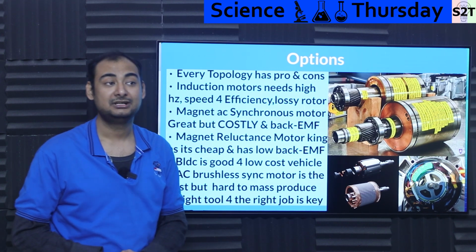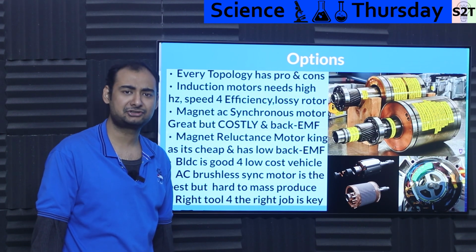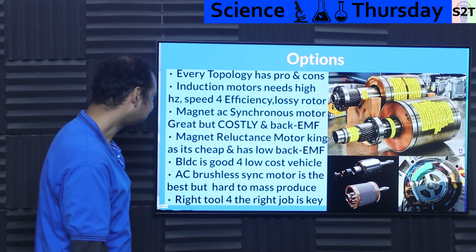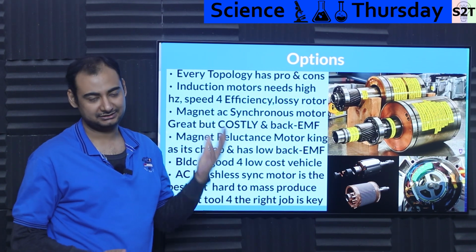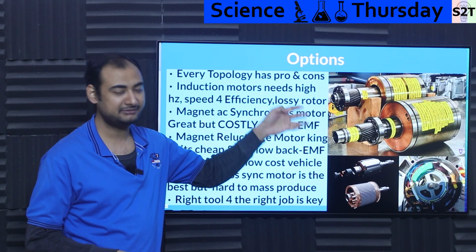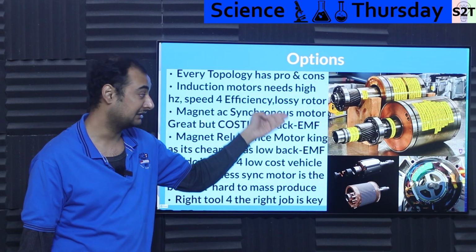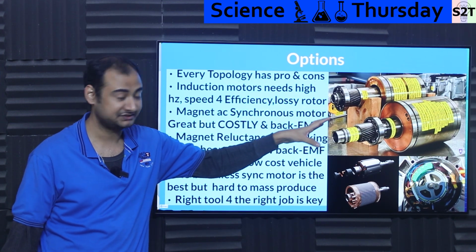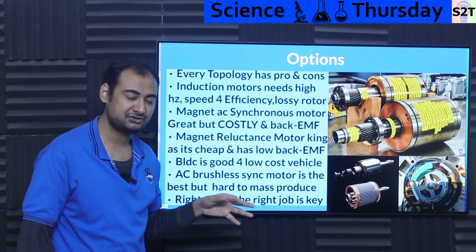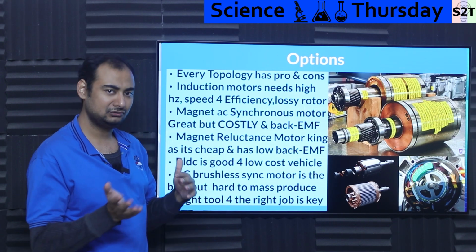That allowed them surprisingly high torque, surprisingly early on. And people were like, how the heck does this electric motor feel so snappy? It's like, cool the rotor. So the induction motor gives you a lot of benefit, but takes away certain things. The biggest penalty is that the rotor is fundamentally inefficient, meaning you have to figure something out. You can have airflow going through it, you can have through hole cooling, but you have to do something with this. And again, it's not synchronous, so fundamentally it will be less efficient compared to a synchronous motor system. So you win some, you lose some.